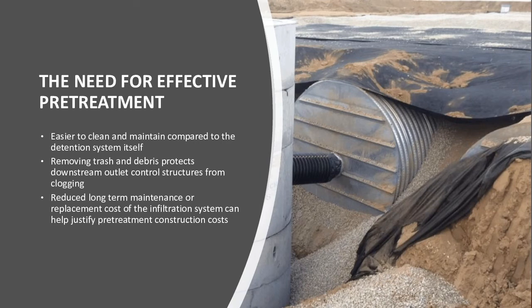We talked about outlet flow controls, but you can also use pretreatment options with these detention systems as well, to try to capture pollutants, or for some agencies they require you to limit the amount of pollutants that come off of a site. Obviously, sediment control can be achieved within the detention system itself, but for some agencies they have requirements for the removal of other pollutants, and with the detention system, the use of pretreatment can be effectively used to remove floatables, sediments, and also some other contaminants before it ever gets into the detention system.